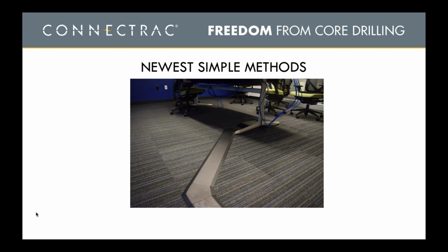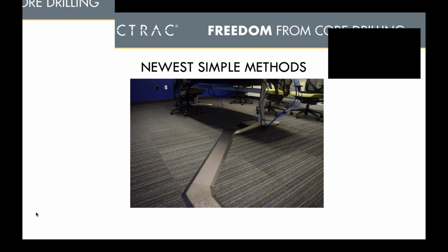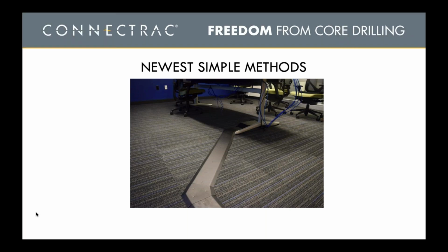The one down and dirty alternative is to simply mount a low profile raceway on top of your floor surface. You might have seen this one, as it's from one of the largest electrical wiring manufacturers literally in the country. It's designed for things like conference rooms, low traffic areas. It provides power and data cabling. It's a pretty simple ADA compliant system.